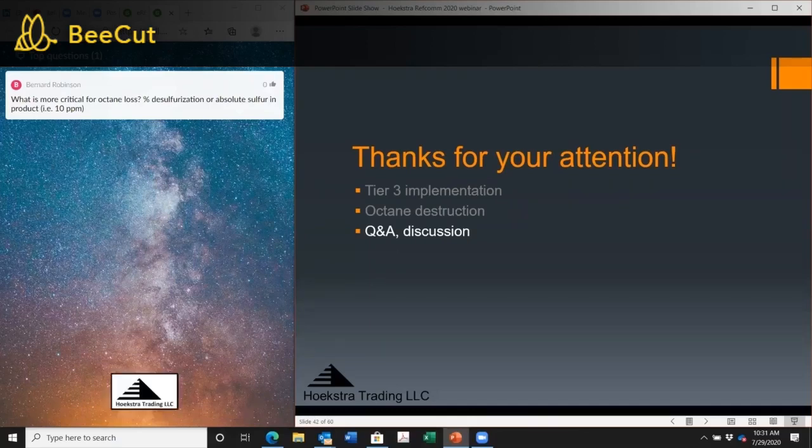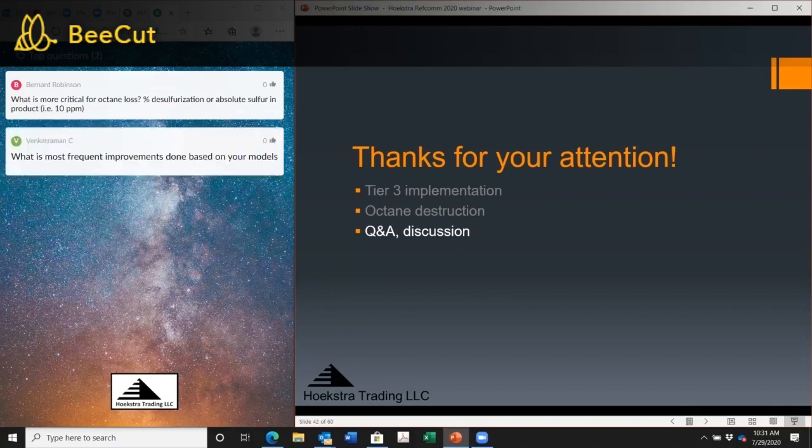Otherwise, you may run it through a catalyst reformer, such as a CCR, to regain lost octane. These are some thoughts. Unfortunately, we cannot modify catalyst selectivity to preferentially remove sulfur, but not saturate olefins and diolefins. Olefin saturation reaction is very easy. That is the problem. Can you add thoughts on that?